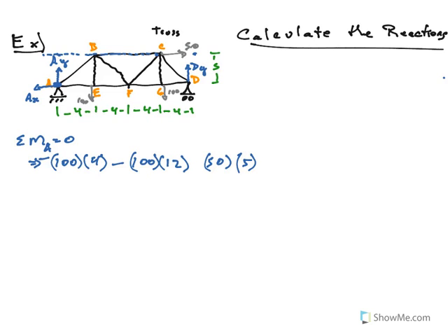So from A up to where C is 5 meters. Okay, C, does that make me want to go clockwise or counterclockwise? Well, again, if I'm holding in place at A and I pull to the right at C, that makes us still want to go clockwise. So he's also negative.